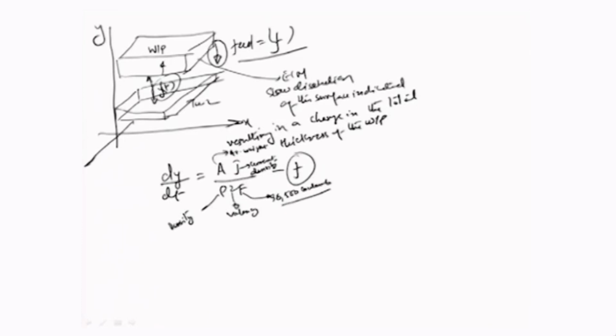So that is what dy by dt would look like. And then if you substitute the formulation for the current density, which is represented by the conductivity of the solution times the available voltage, V minus delta V, where delta V is the overvoltage potential which has to be given in the design voltage so that the amount of machining that you intend takes place, divided by y, where y is the gap.